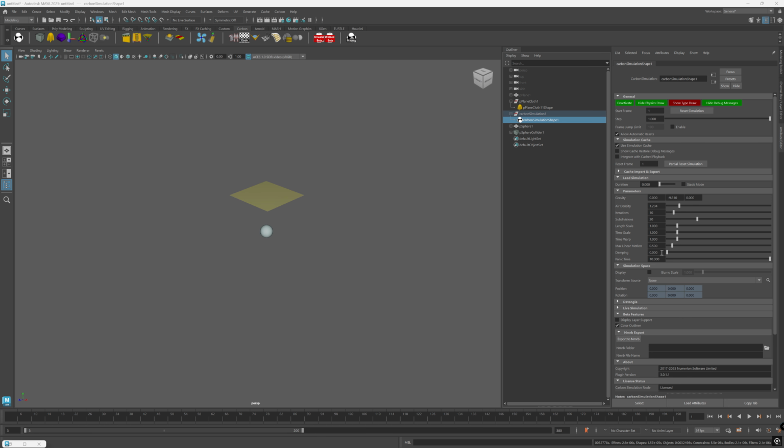Damping. This is a damping force coefficient. It behaves similar to having a uniform flow in the scene. It just dampens all behavior and removes some small oscillations and wiggles when used sparingly. Normally we recommend using a factor of 0.1 or maybe even 0.5 if you want quite a lot of damping. In the scene you won't see much of a difference because it's already pretty calm, but it's going to reduce some of the swinging here.